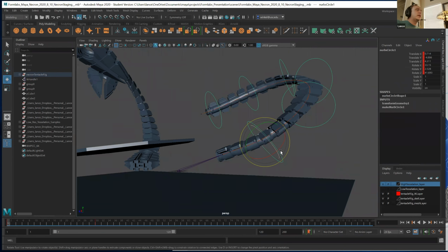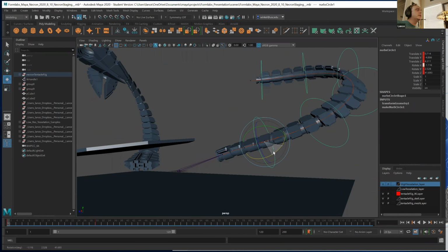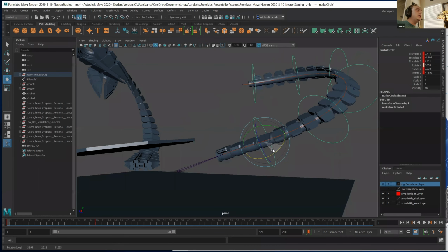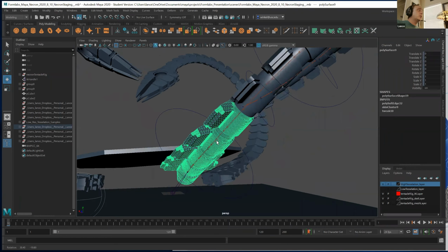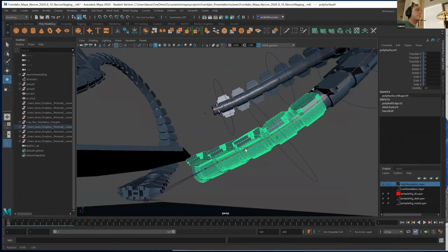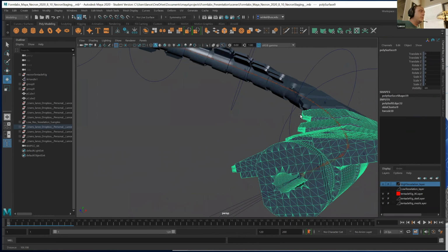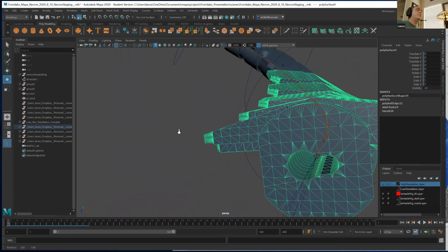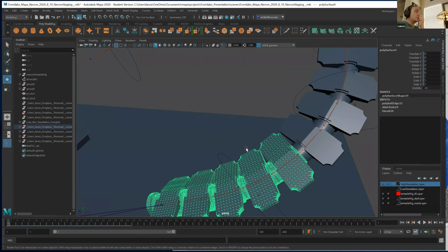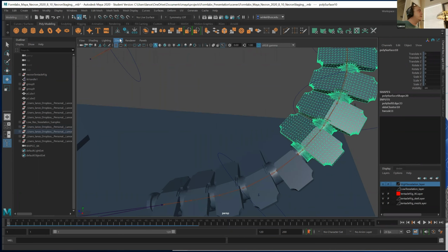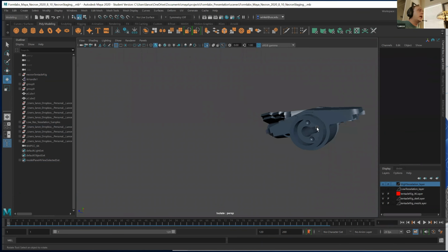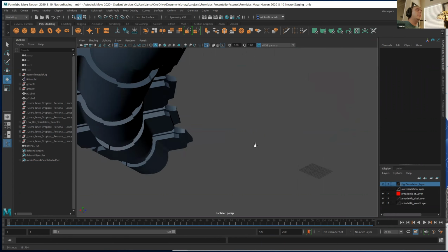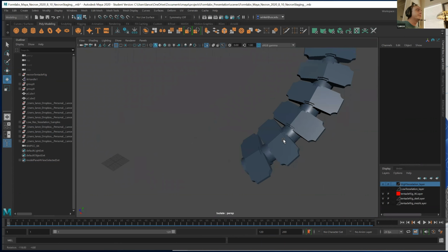There's a lot of resources out on the internet that can get you understanding of how to do this type of stuff. But by me taking what starts off as, these are actual STLs exported out of, these by the way came out of Fusion 360. I had already built in all of my wiring. I had already planned in my channels for where the LED wires were going to be. I had even built in all of my plugs and glue mounts and points where it was going to solder together. Okay. But then I bring it back into Maya.